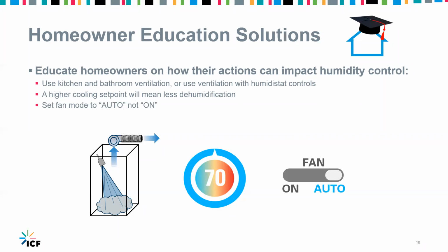And last thing is for your thermostat, set it to auto, not on. If it's on mode, that's going to waste energy. It's basically going to cause the same issue I described when I talked about supply fan overrun. So I'm sure for lots of you, this has put some ideas in your head on things you've seen people do.